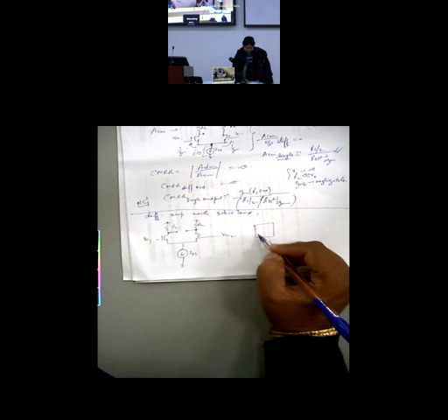But tapping the output differentially means you get the output from two nodes, one positive and one negative. So if I have a next stage to it, that should also have two inputs. That means a differential amplifier has to be followed by another differential amplifier.